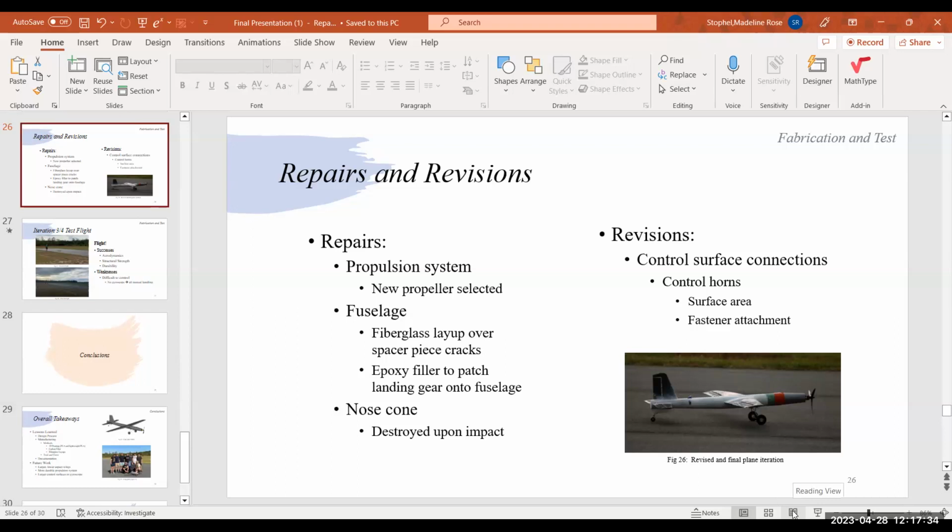It looked like your plane was actually super responsive to roll, and my first two thoughts were that maybe the plane was really light, or maybe there was a lack of lateral stability. In real life, I think with the current fuselage design, you have the wing going straight through the middle of the plane as opposed to a high wing, and that may help you a lot with stability. It feels like you tried to design for a high wing, but in this case the wing is sort of dead in the middle of the fuselage, and I think that's why your plane was so responsive to roll.